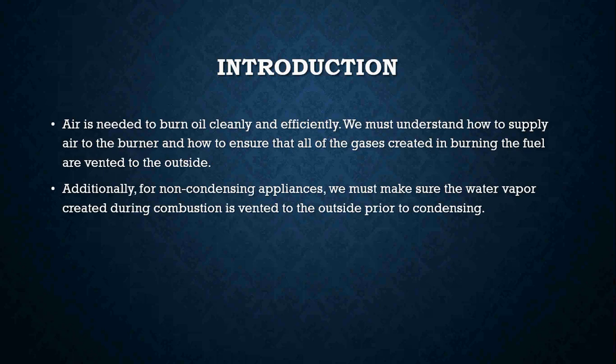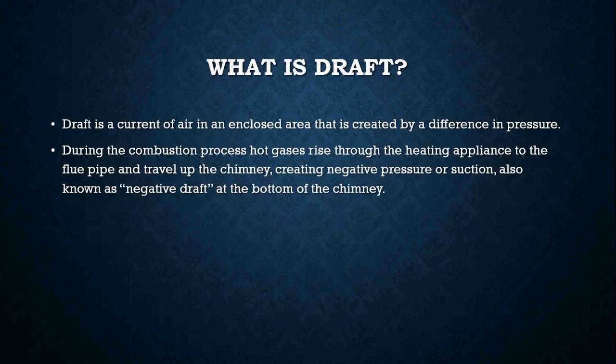Additionally, for non-condensing appliances, we must make sure the water vapor created during the combustion process is vented to the outside prior to condensing inside our flue pipes. Because we know that if water condenses inside the flue pipes, it can start to corrode them, right? So we want to make sure that that's not happening to begin with.